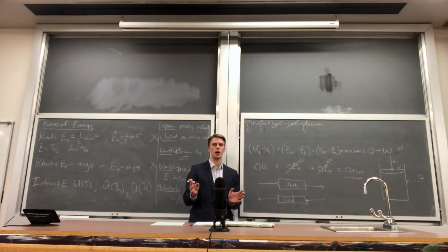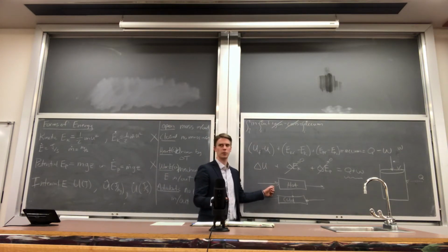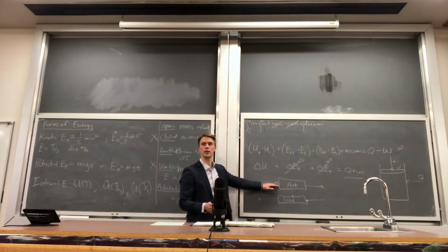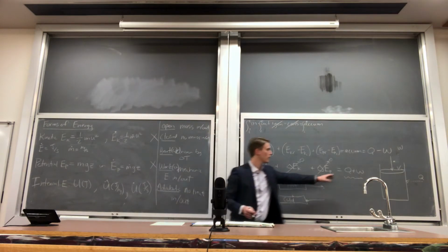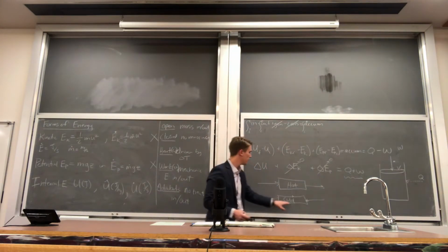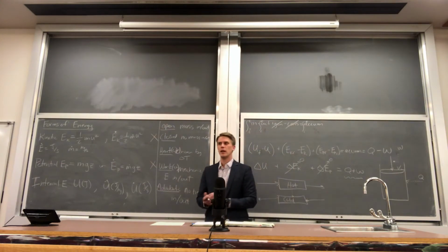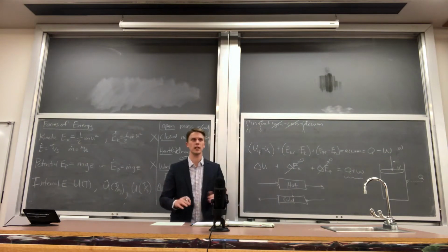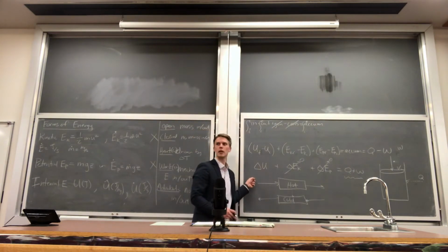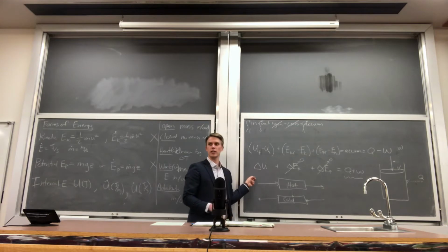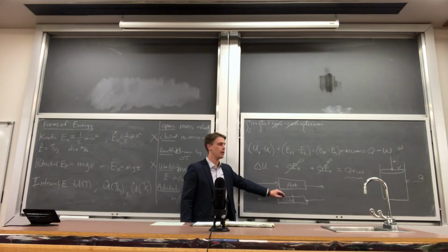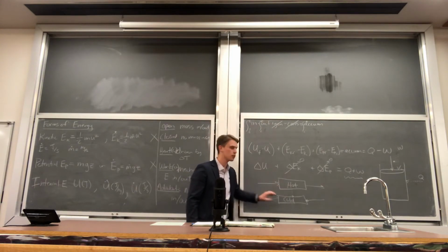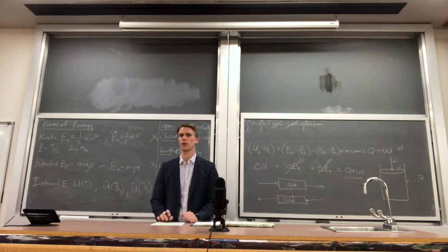But when the processes get more complex, you won't necessarily know which is the hot side and which is the cold side. But in this convention here, if I were to do an energy balance on this system, I should minus my Q. Oh, that violates this convention here again. And on this side, I should plus my Q. And if you keep the arrows in and out consistent, then you don't have to be changing positives and negatives from doing a balance on one system to the other. That's going to be the key critical part, because let's say, for example, we were to change the convention halfway through. That means it would matter whether you did a total balance, a hot balance, or a cold balance, how you have a plus or minus, and you're just going to throw things off badly.